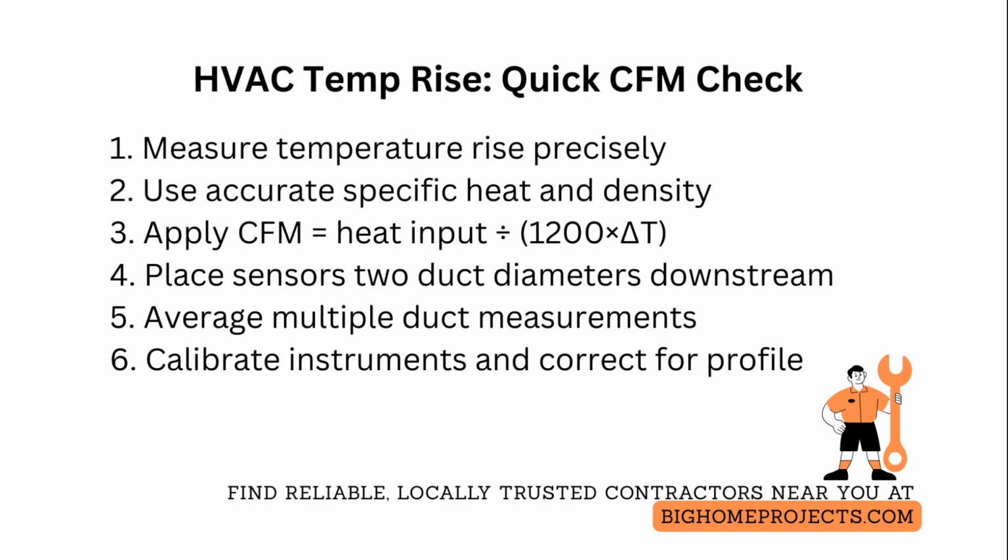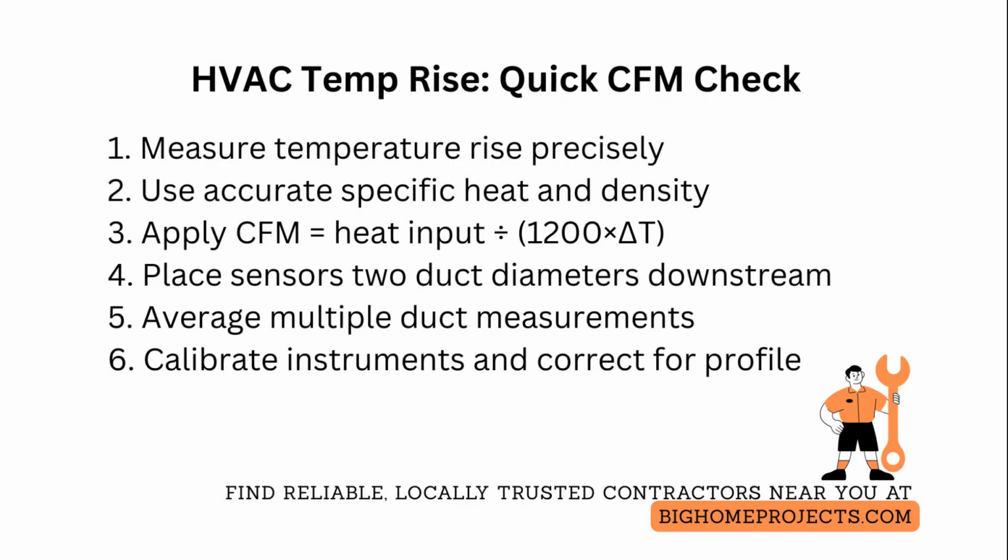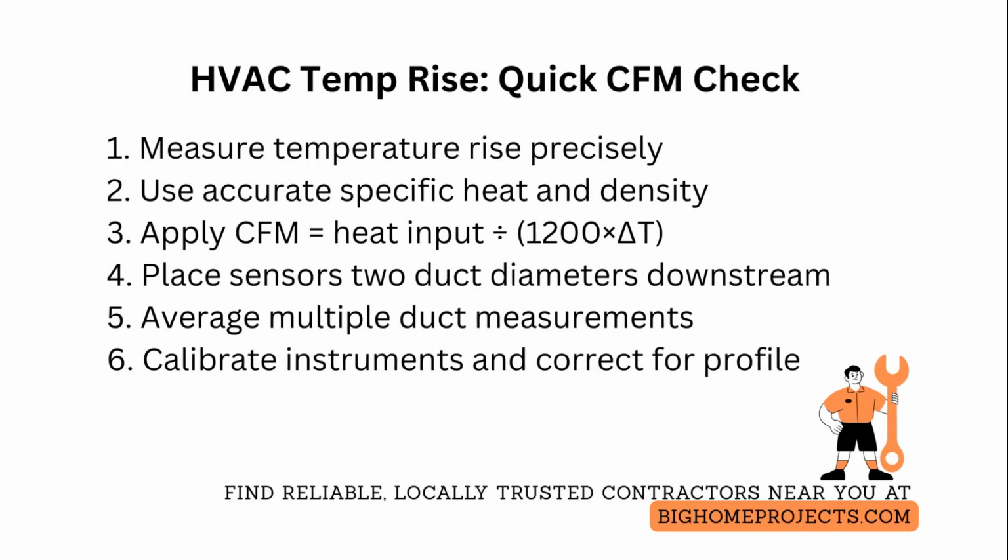If the job requires high accuracy, weigh anemometer results against the temperature rise method and an independent flow hood at terminals, and reconcile discrepancies by checking for bypasses, return leaks, or unaccounted bypass dampers. Always log ambient conditions, fuel type, and controller set points so calculations can be audited and repeated.